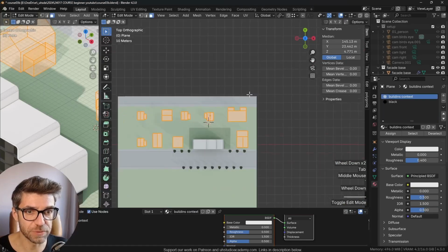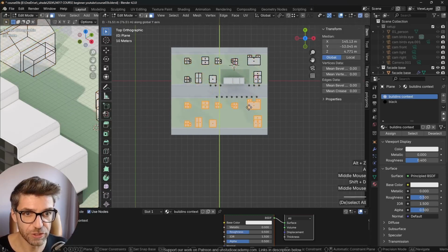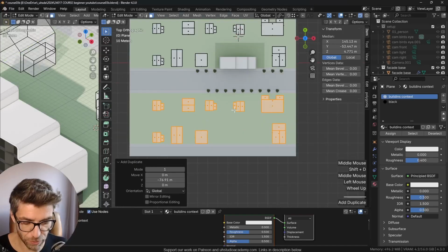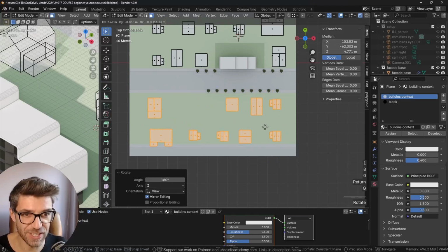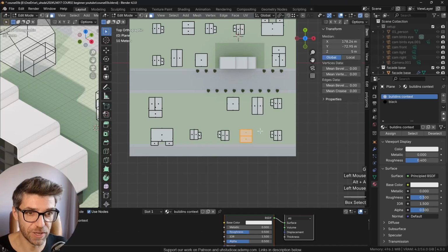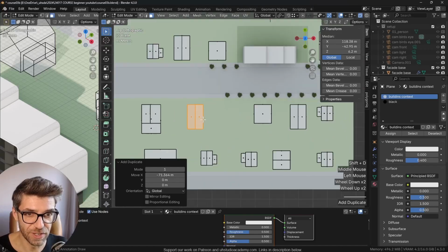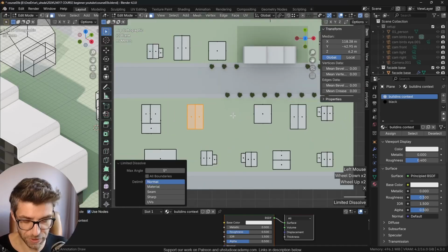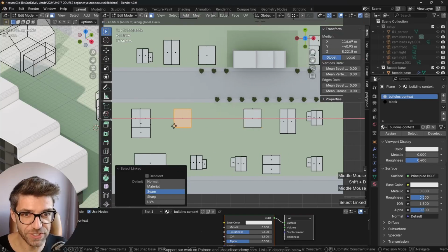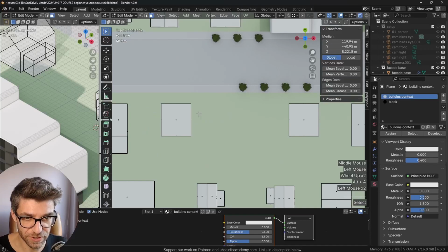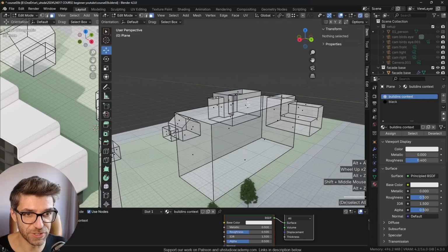probably because it's our building. I'm going to select everything in here now, A to select, duplicate it and just move it over here. Maybe rotate it 180 degrees, so it's not exactly the same. And now I'm going to copy what? Let's duplicate this to somewhere over here. You know what? No, we're going to have a big building over here as well. So X faces, L to select this, Shift D and move this edge to somewhere over here. So that building is a bit chunkier here.